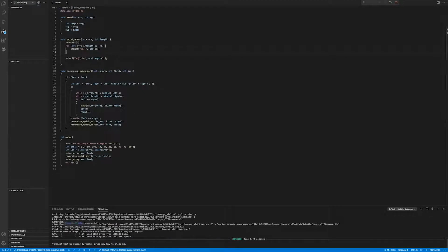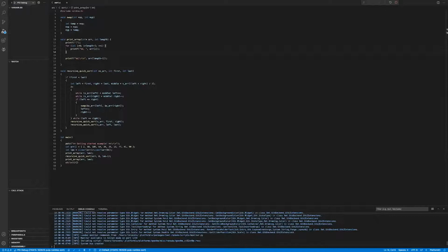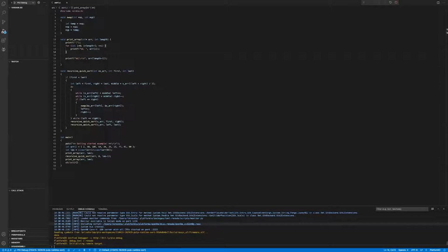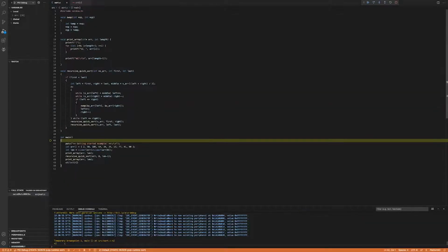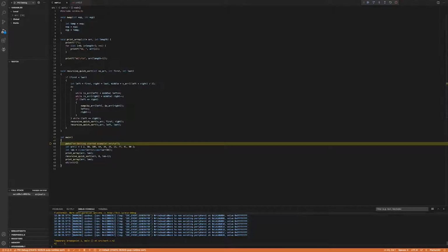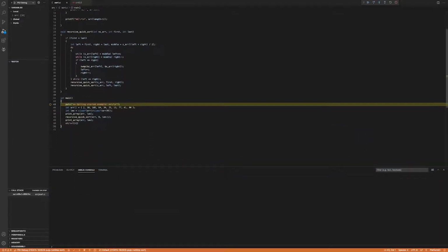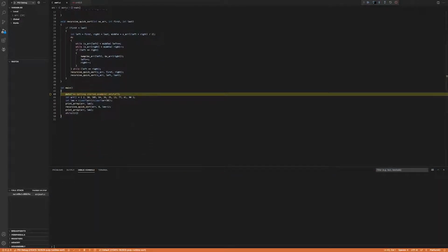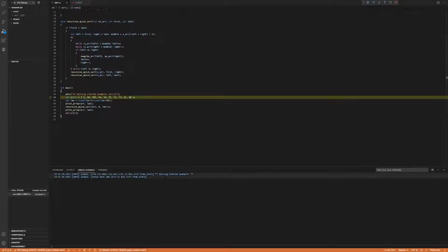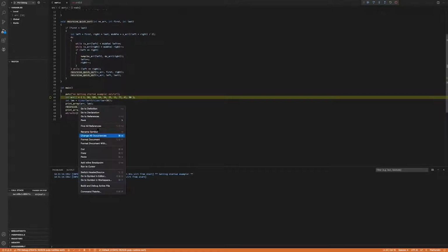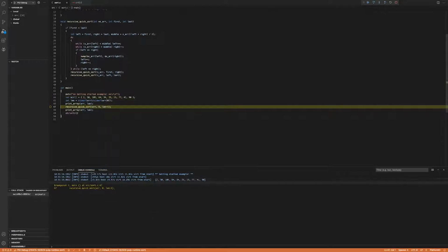The project is compiled in debugging mode, and now we see in the debug console that Renode is started. We should wait a few minutes until the debugging server connects to the front end, and we should stop at the main function. We can step through our code. Now let me try to clean the debug console, because the next line is the print line. You see the getting started example. You can go next. You see the getting started example. You can go to any line, like run to the cursor, and we see it works.